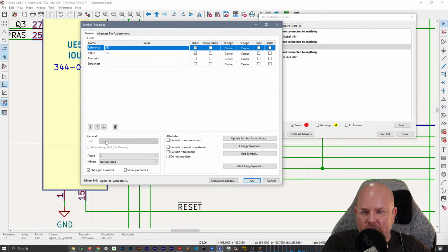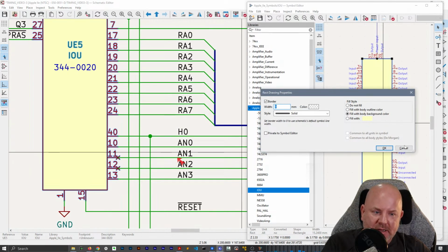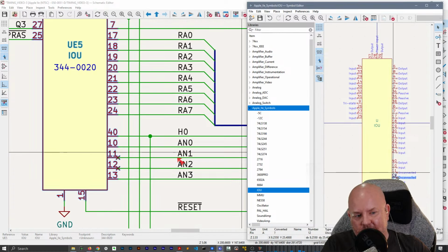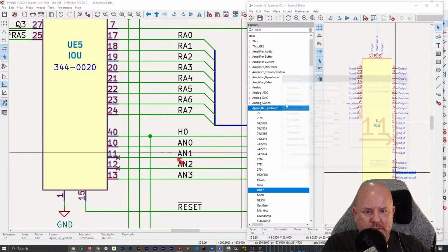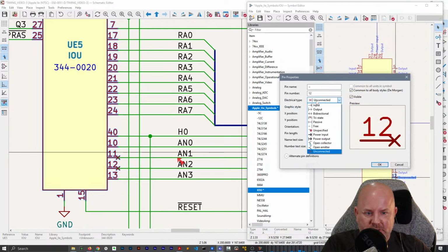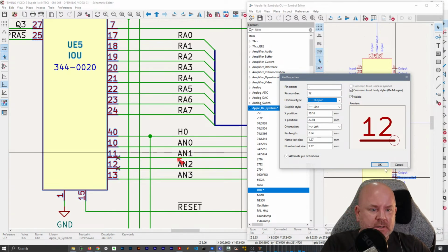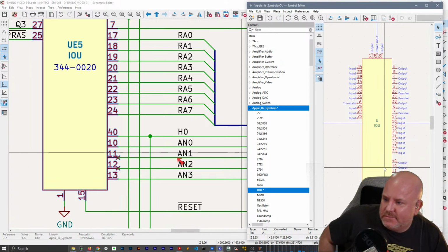The enunciator pins, I don't think exist in the 2C because it doesn't have the 16-pin connector. Duh. And I copied the pin assignments from the 2C IOU, which is different from the 2E IOU, as I explained earlier. So this is actually supposed to be an output, and this is supposed to be an output. They're called the enunciator. They're basically 3 GPIOs, well, general purpose outputs from the Apple II. And in fact, on my Mega 2E, I used these to blink LEDs. Because why not?